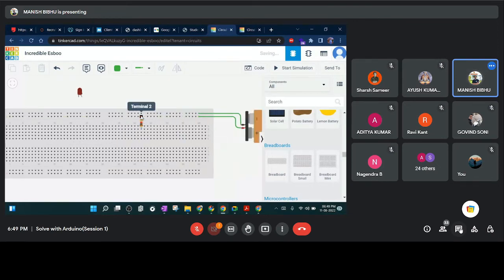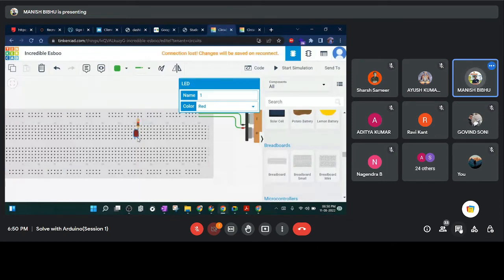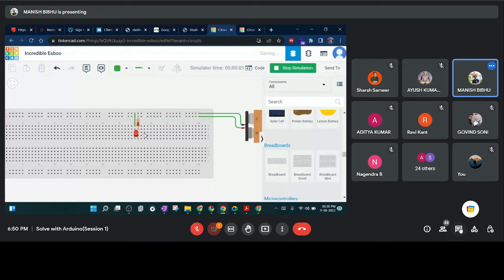Here I have connected positive to that terminal. Now the whole column is connected to the positive terminal. If we remove the resistor from here, it is not connected to any supply. So we connect this column to the positive supply, and we can connect an LED in the same column to any hole, and now we will connect that hole to the negative. Now it is working.